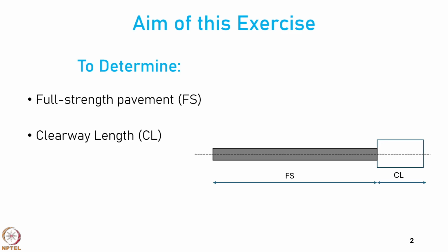Then there is also a clearway, which, as you probably remember, is an open area of land under the control of the airport authorities, which is clear from any obstacles unless they are required for safe and expeditious operation of the aircraft, such as the taxiway lights, runway lights, etc. It is a piece of land which is clear of obstacles, allowing the aircraft to climb after liftoff to achieve the obstacle height, and it can also be used for the approach of the aircraft while landing.